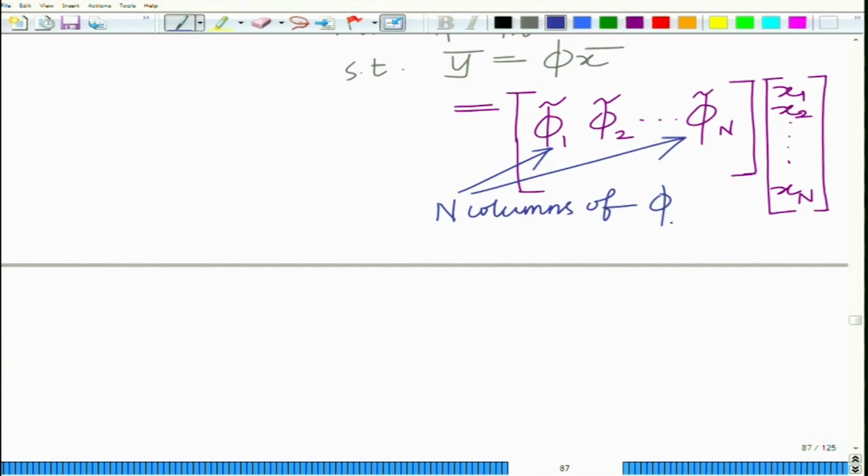Now, the orthogonal matching pursuit, remember the name itself implies matching, alright. So, you are looking for something that matches. Okay. What is the thing that matches? You are looking for the column that closely matches the vector y bar, which means basically you have to find the projection of y bar on each of these columns of the matrix phi and choose the one that has the maximum.